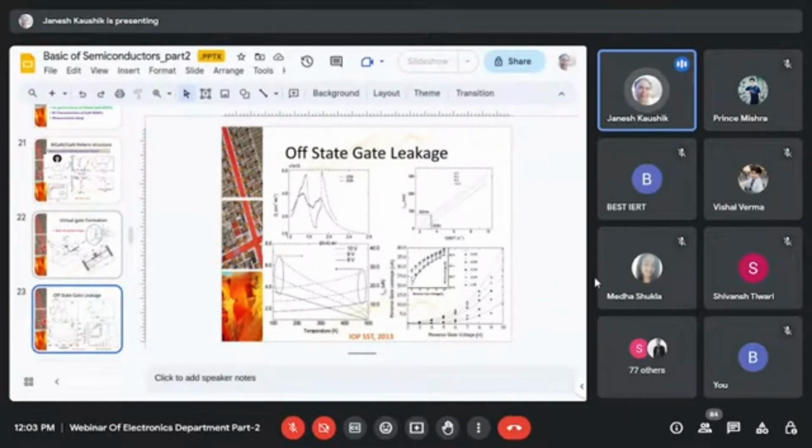The D_it we have calculated here is from the forward IV measurements. In the forward IV measurements, we calculate the ideality factor that we discussed in the last class. That ideality factor we can correlate directly with the interface density, and that gives us the surface states distribution.